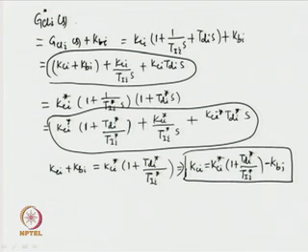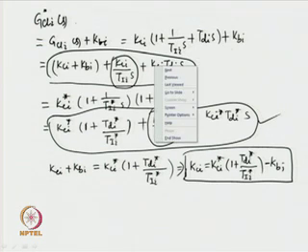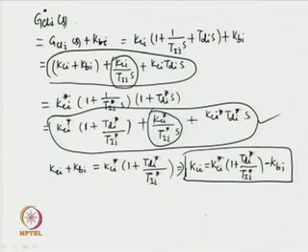Using the other terms upon comparison, this term must be equal to this term, because we are comparing the dynamics of the transfer function form of the new controller with that of the parallel PID controller and the additional proportional controller in the inner feedback path.